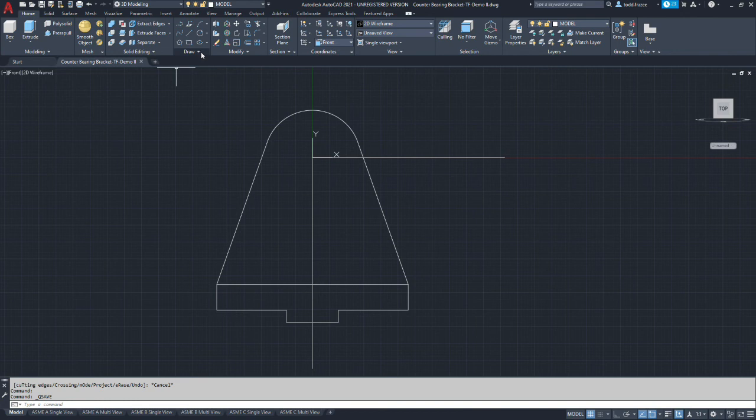We're going to start with the base flange profile, and we're going to select the components of that shape we want to extrude. Once you have the whole chain done, hit enter, and it should say one region created. Okay, now we want to make another region that's this tapered flange profile, but one of the lines is common. So you can see how when I hover over this, this whole thing will highlight. So we're going to need to make an additional line segment that connects those corners that can be part of this other region.